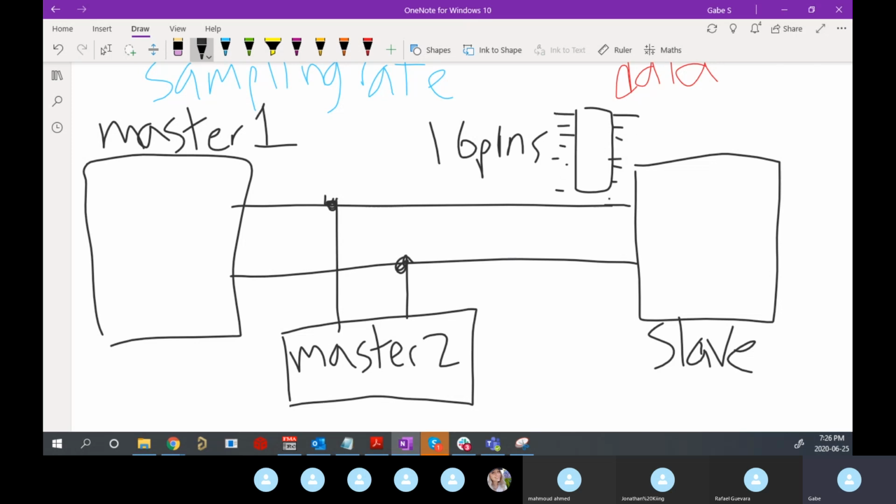In contrast, VCU has 144 pins, so that's a lot. If you're limited on pin count, you have a bunch going to GPIOs, some going to ADC, some going to PWM, some going to power and ground. You probably want to limit the number of pins you're using for communication, so with just 2, you're able to communicate to all your sensors. So I think that's a really good application of I2C.